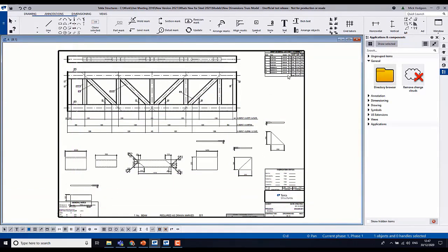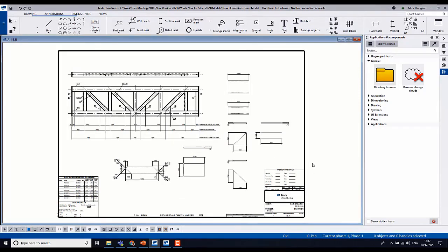And I'm going to select the final template, right click on there, exclude from the drawing, move it along, reposition it down, and it's in its new location. If I now arrange those drawing views, it takes those into consideration and arranges the drawing into the position and format that I'm happier with.